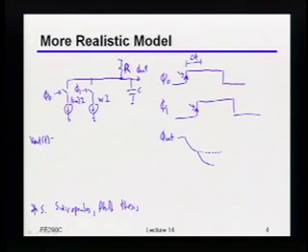So in other words, if we actually write this out, so if we want to know what the output voltage is as a function of time, it's just going to be VDD minus I times R times the sum of two things. Okay? So how would you represent the impact of the first input, meaning the phi 0 input? And let's just say that phi 0 goes high at time t equals 0.